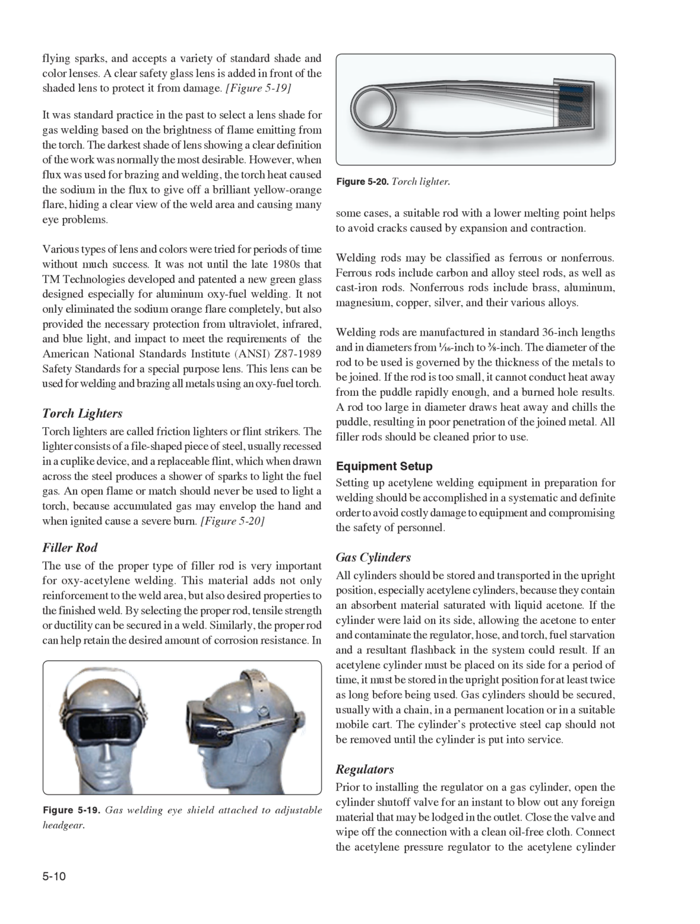Figure 5.20. Filler rod. The use of the proper type of filler rod is very important for oxyacetylene welding. This material adds not only reinforcement to the weld area, but also desired properties to the finished weld. By selecting the proper rod, tensile strength or ductility can be secured in a weld. Similarly, the proper rod can help retain the desired amount of corrosion resistance, and avoid cracks caused by expansion and contraction.